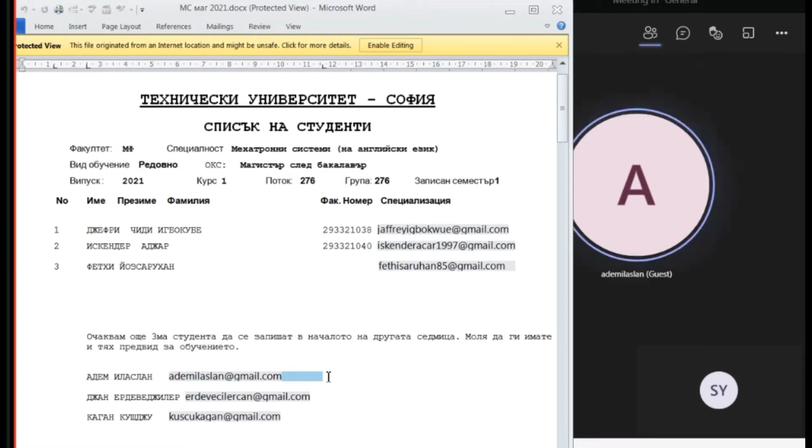We take a block, we move it in a new model, connect blocks, assign parameters to the functions that are performed in each block. Then we assign some general parameters for simulation, for instance, simulation time, step time with respect to discretization in time.